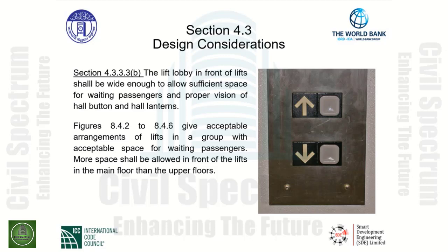More space shall be allowed in front of the lifts in the main floor than upper floors. It should be noted that it is preferable that the lift lobby is not used as a thoroughfare as well. But when absolutely needed, the lift lobby shall be wide enough to take into account the space for people who are moving.